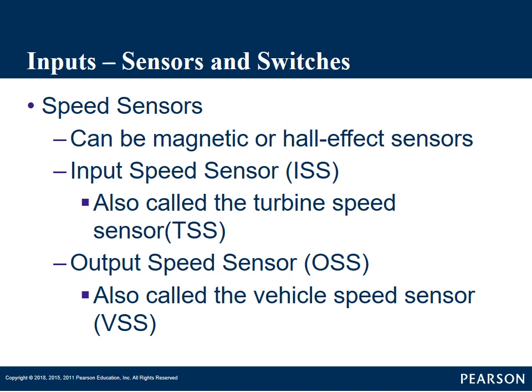If that torque converter is supposed to be locked up to where there's no slippage or very, very little, and they monitor a lot of slippage, they're going to turn a light on because you could ruin your transmission, or it's definitely a sign of a bad torque converter. So what they do is they monitor their output speed of the transmission. They've already factored in gear ratios, determining what gear you're supposed to be in, and then they monitor engine RPM if they don't have an input speed sensor.